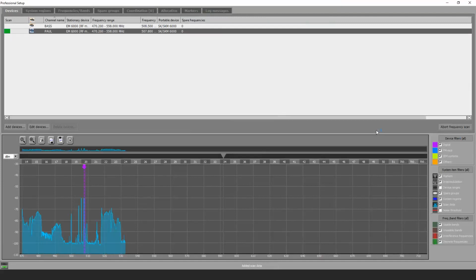So taking a look at it, you can see one thing to think about. In the U.S., most of the public safety type of transmission, for emergency response, first responders, is down in that 470 to low 500 megahertz range. So you do want to look at that, and we may be seeing some of that right here with these spikes down below. If you did the same scan in LA, very, very busy down in this area. So take a look at that when you do scan your area and see what kind of interference or activity you're seeing down below. Now, one thing that's not good about this type of scan is that it's a one-time scan as opposed to a real spectrum analyzer that's constantly refreshing, but still a good tool for you to get a good look at what your system is seeing.